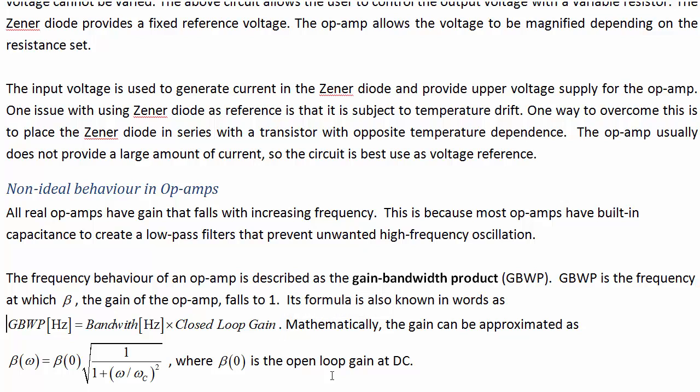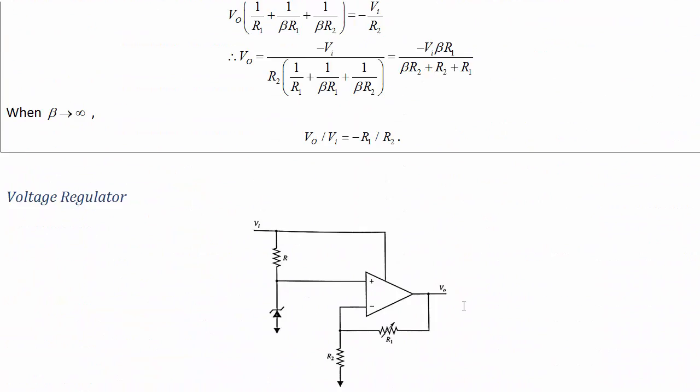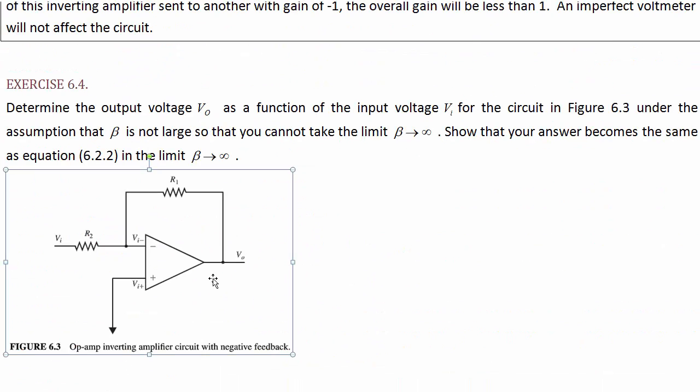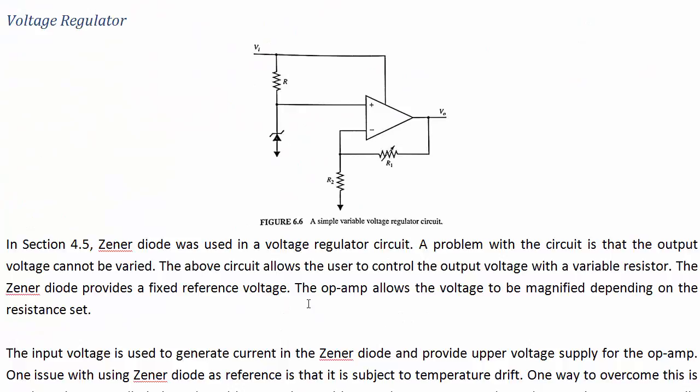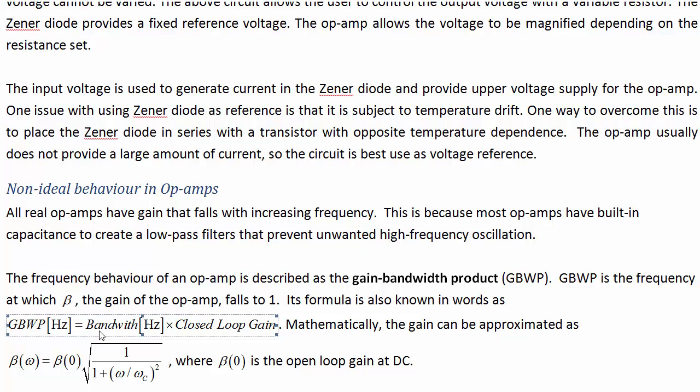If you were to make a closed loop gain in your circuit which is 1, so you suppress the intrinsic gain like we've been doing in say the inverting amplifier circuit by picking resistors so that the closed loop gain is 1, then you would find that the bandwidth where your op-amp circuit actually gives you this output gain of 1 would be equal to the gain bandwidth product.